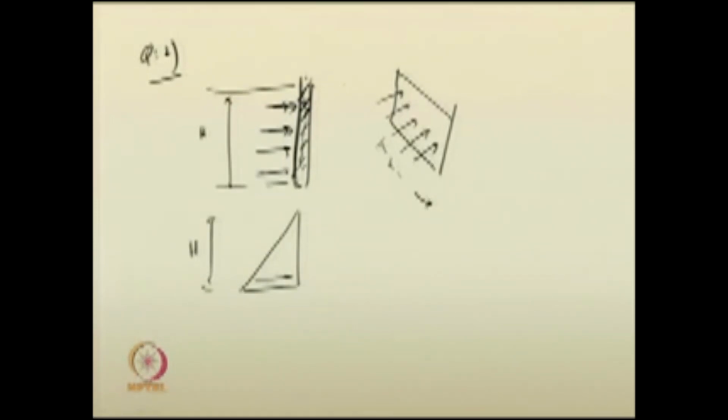So, if I draw it in this particular form, and water, this is the length of the sluice gate, right, and you will see that pressure force acts perpendicularly to the plane of the sluice gate. This pressure force is caused by the depth of water. This is the height h, and pressure force is obtained by getting the pressure multiplied by the area of this triangle.